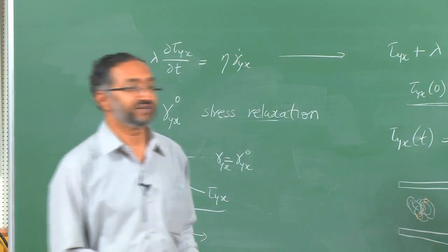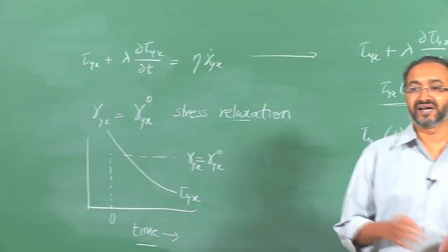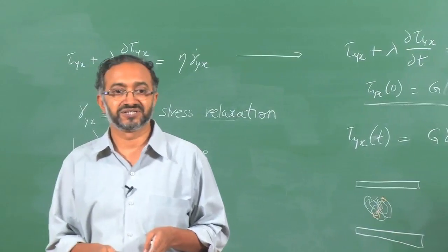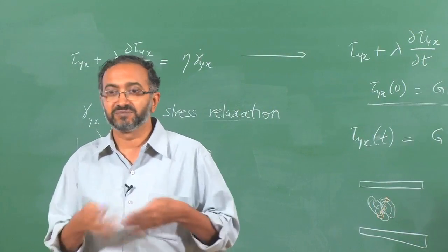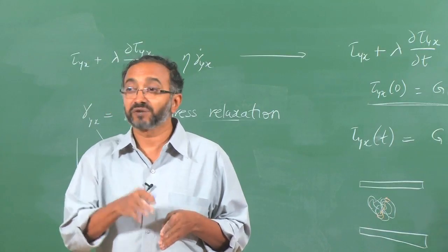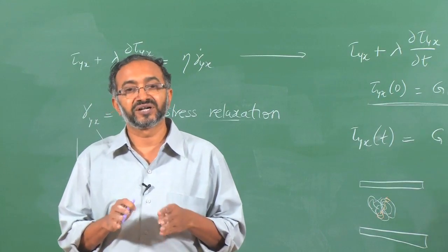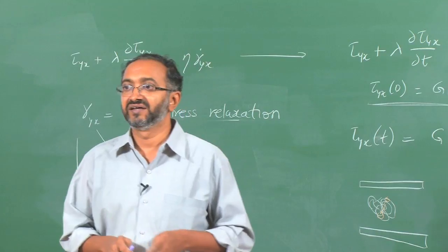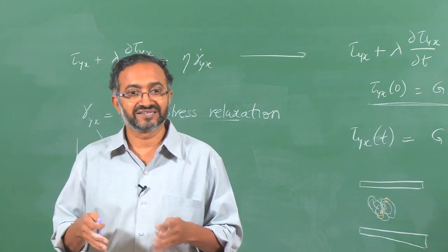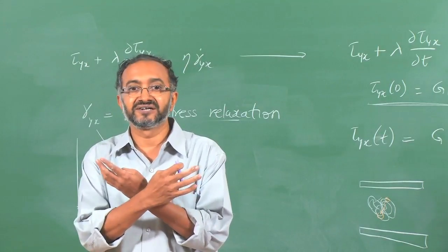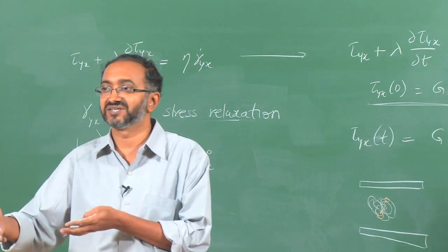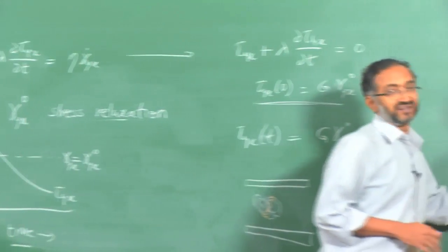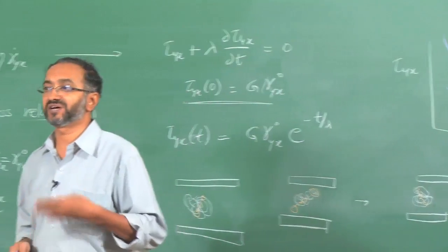So therefore I can try to fit multiple exponentials, and then I will say that, oh, looks like the material that I am studying has in fact multiple relaxation processes, and if I assume that, then I have to look at, of course, the material makeup, I will have to make a hypothesis of what might be the relaxation processes. I will know that, oh, there are some bond level or segment level phenomena, so that will be a shorter time scale. Then let us say if it is an entangled polymer melt, the way we discussed, polymer molecules are entangled, so therefore there will be very slow relaxation processes. So then I can clearly see, by studying stress relaxation, I can try to see what are the relaxation times or relaxation modes which are present in the material.